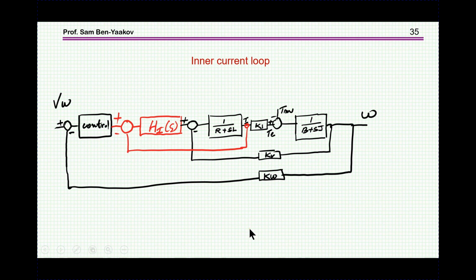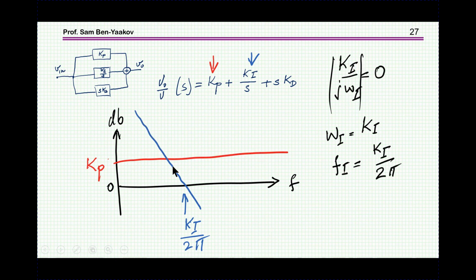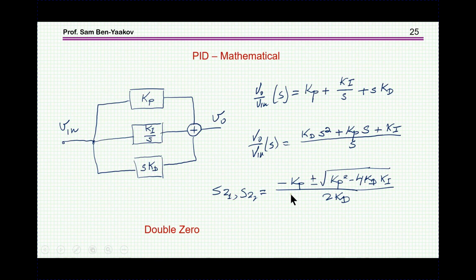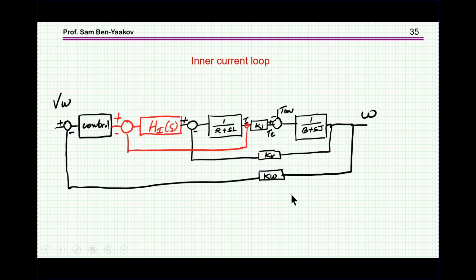One way is to use a high order compensator. Another way is to try to reduce the order of the system. That is, rather than dealing with a system which is second order, as we have it here, due to the fact that we have the mechanical and electrical part, there is a way to modify the inner transfer function by an extra inner feedback in the loop.